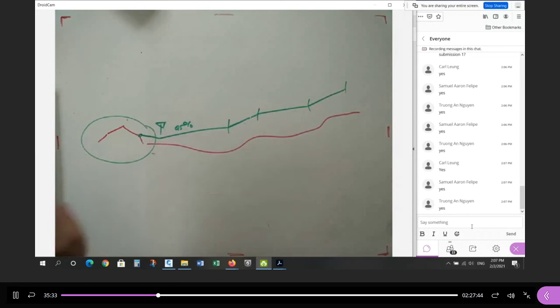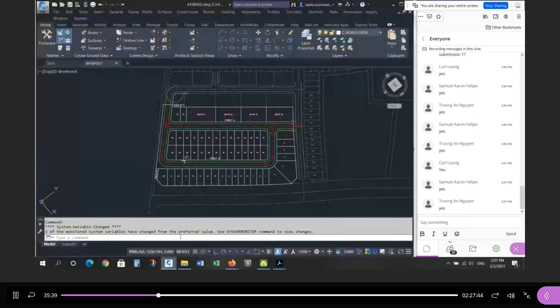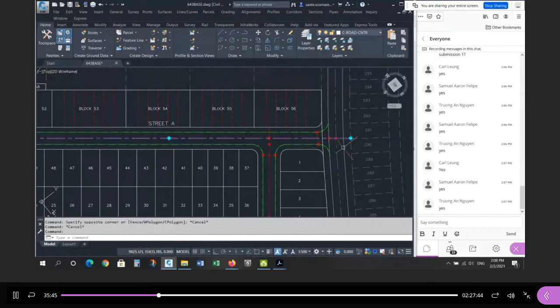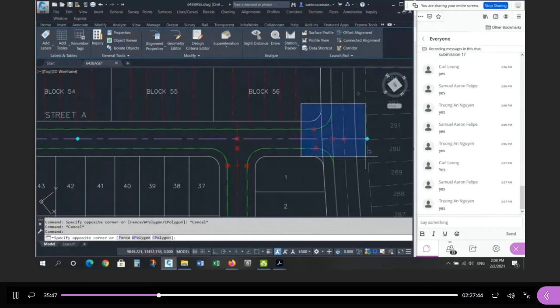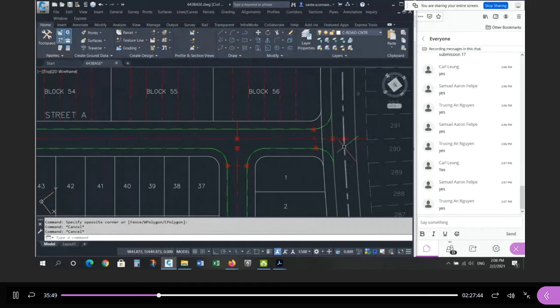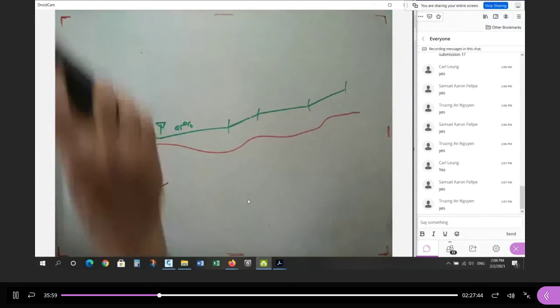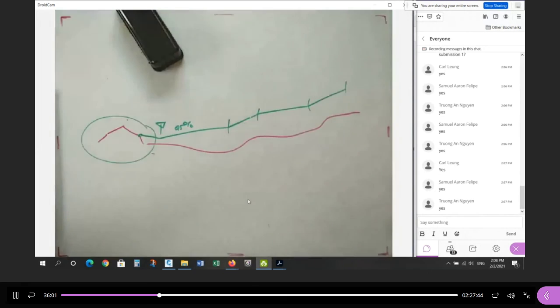Okay, so when we look at the existing ground profile for this particular design, you're not going to see the existing road cross-section. I'm talking about Ledger Way, let me go to the drawing. When I look at the profile of Street A at this end where 0 is, I would hope to see an urban road section, right? Actually it would be at the other end, because we're looking at it backwards.